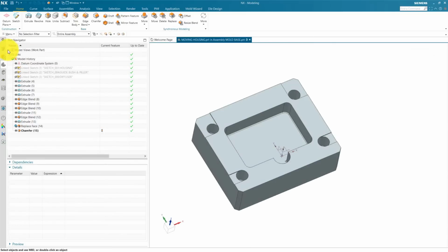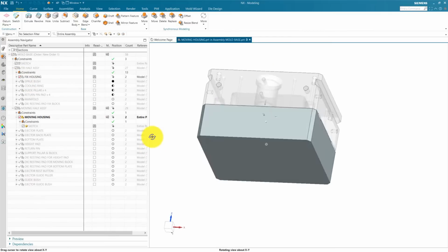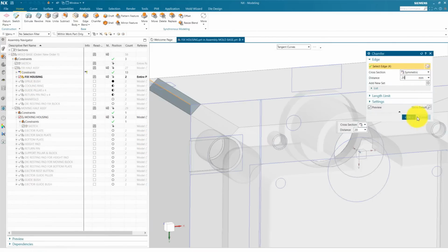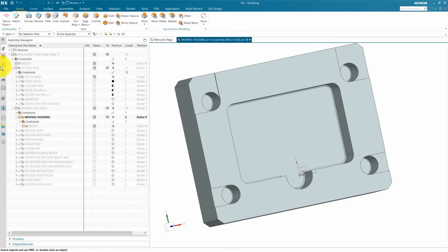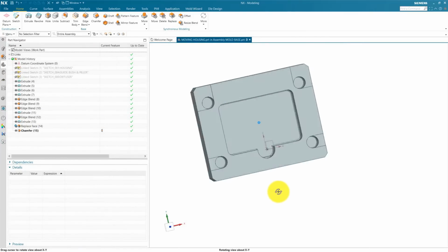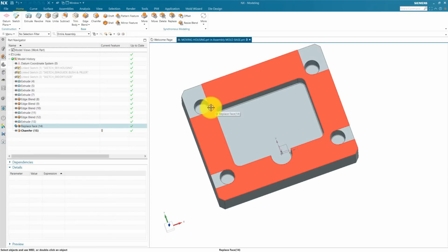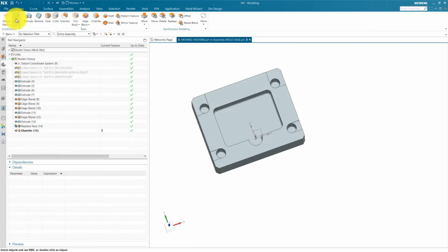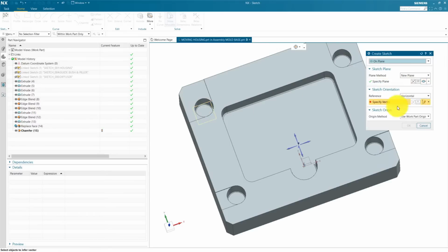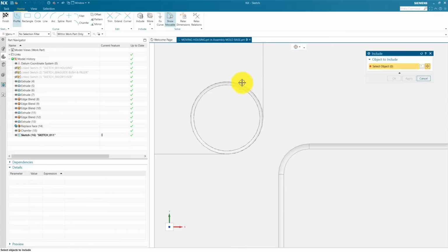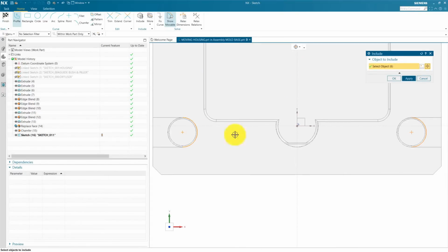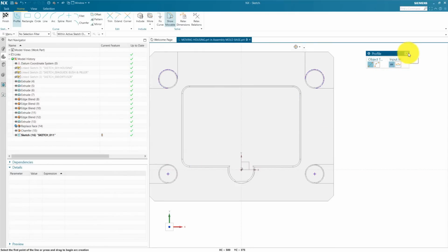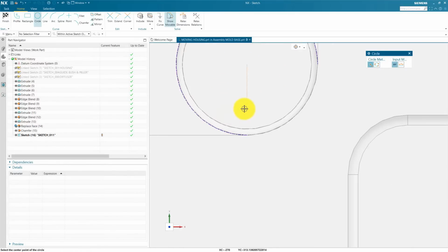20. Make sure this is similar to our fixed housing. Okay, now we are going to add some hole for an air vent inside our guide bush hole. This hole is also present in the guide bush. For this we are going to sketch, select this face, define a horizontal reference, press OK, include this circle. The center is also okay. We need a center. We are going to create a hole.